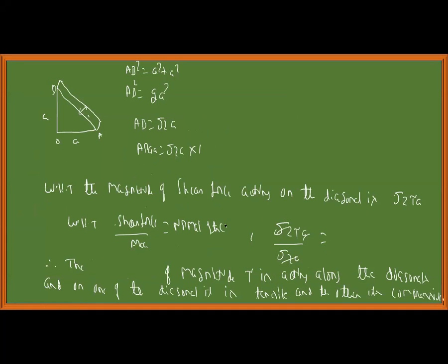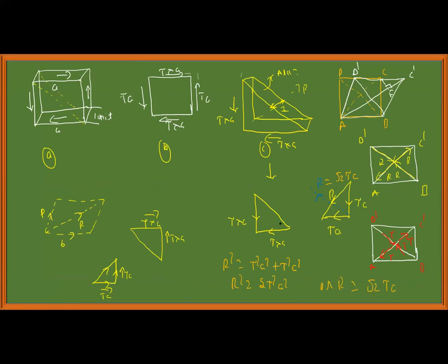The normal stress or axial stress, of magnitude tau, is acting on one of the diagonals and is tensile, and the other diagonal has the same magnitude tau and is compressive. Even though normal stress is indicated by sigma, in this case our normal stress is tau.